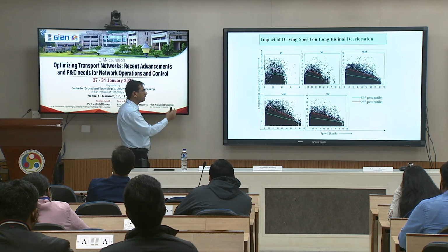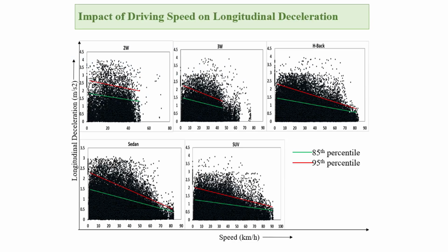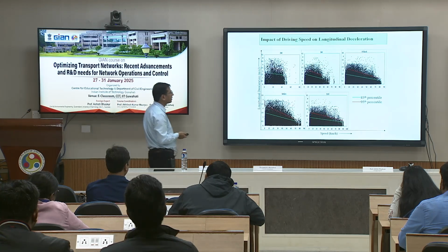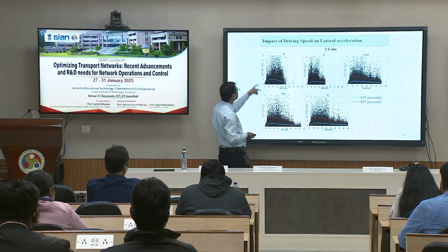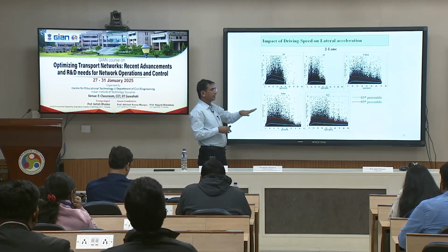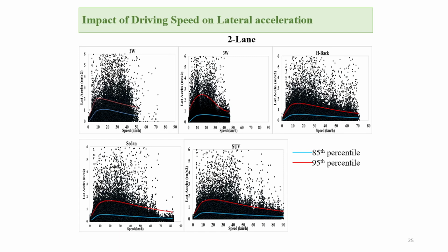Okay. So all these acceleration and deceleration extreme values you might require in your simulation, so that you have customized acceleration limits for Indian conditions. Okay. Then this is lateral acceleration. Lateral acceleration comes into the picture if you do serpentine motion. How quickly you are shifting laterally, this lateral acceleration is going to govern it,